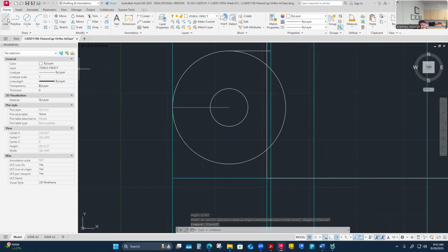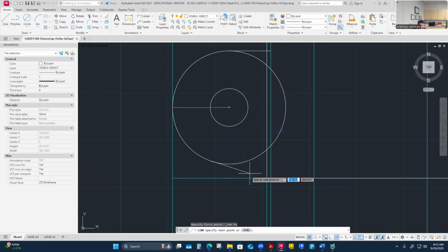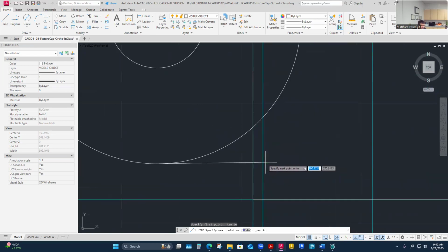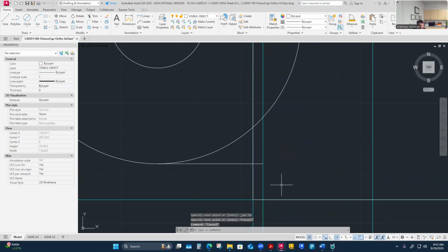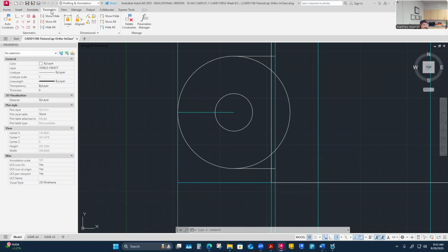Yeah. And I think I'll do the same trick here: I'll shift select tangent there and then shift select perpendicular. So this is how I can force it; it's going to force itself to go straight over just by the geometry that I've chosen there. We're going to be doing more of that kind of work in the future when we actually draw parametrically. I keep promising you this, and it's going to come. I love this tab, and we haven't even used it yet. It's the parametric tab.